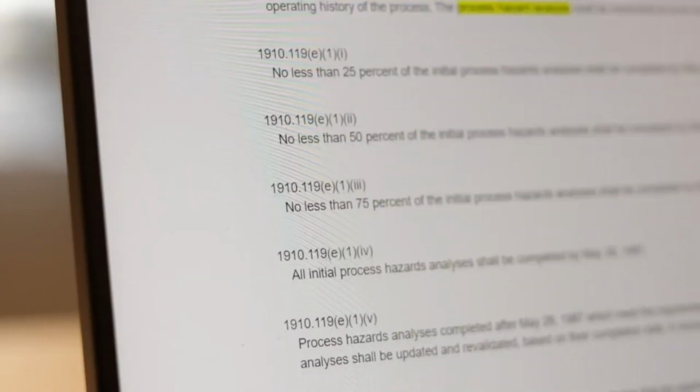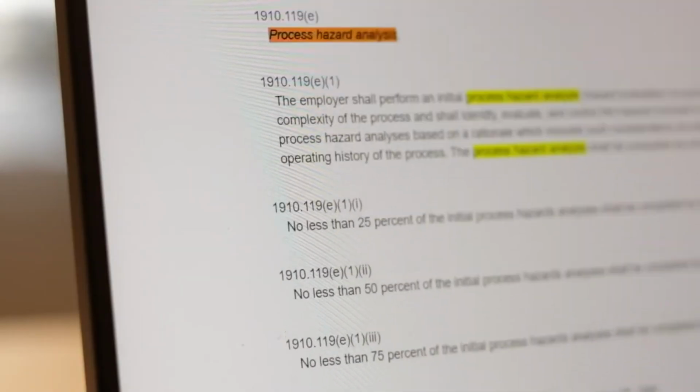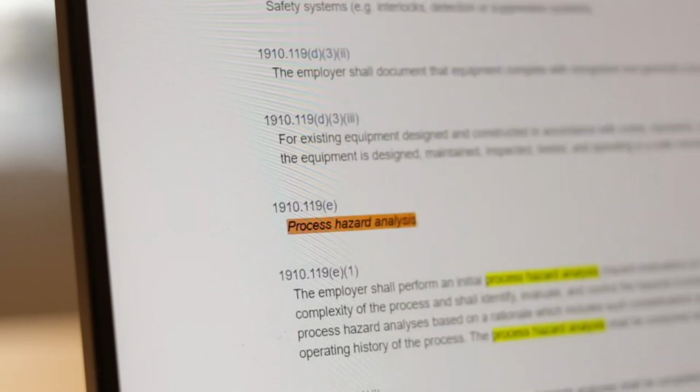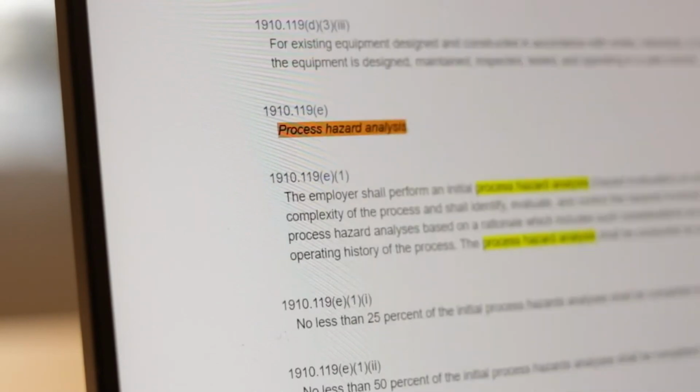RMP and PSM regulations require that process safety information be developed prior to conducting a PHA. Therefore, one can conclude that it is unacceptable to complete a PHA when the P&IDs are absent. But if having P&IDs available is simply viewed as a formality, the PHA team will not reap the benefits of these drawings. Often, P&IDs will assist in visualizing and analyzing the scenarios being examined.